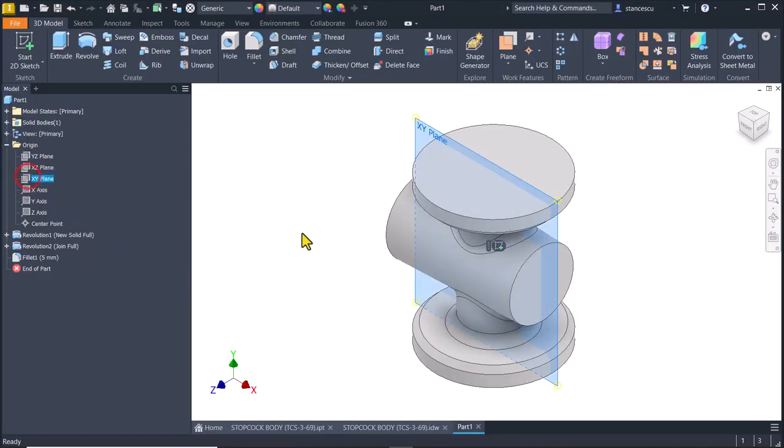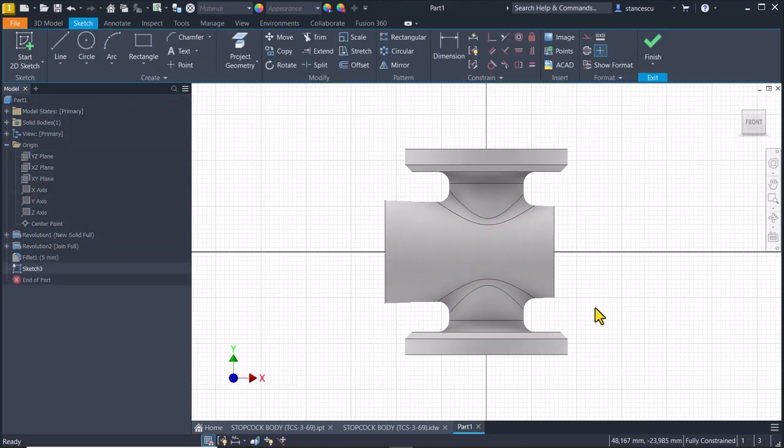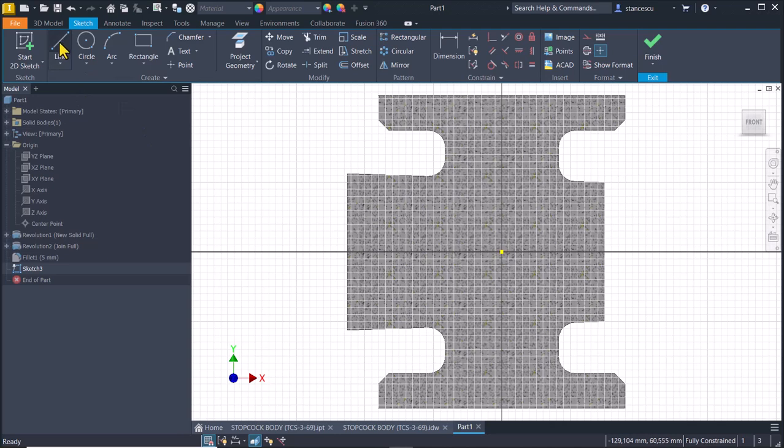Again, XY plane, F7. We draw a horizontal between midpoint and midpoint. When you see green, this means that this is fixed, not mobile. And we apply axis. Line from a point on this axis, down, right, up, to the face, and this is the other end.